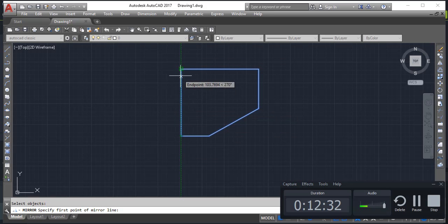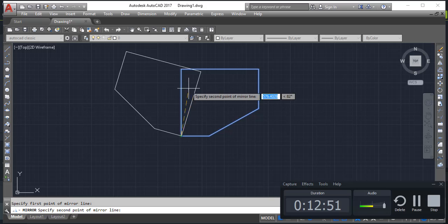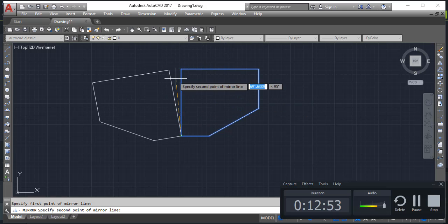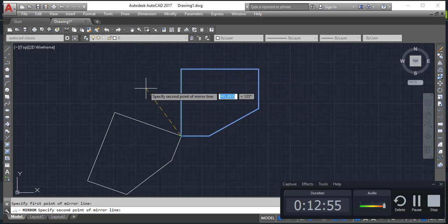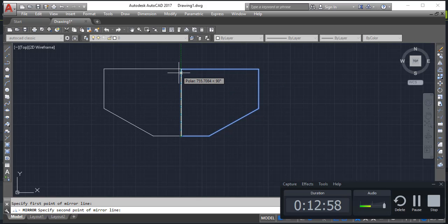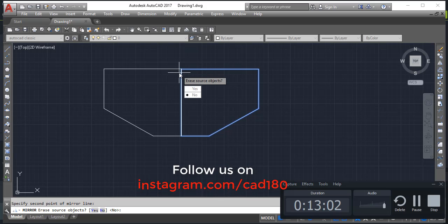So I just take this line for my mirror portion because I want these portions of this drawing to cover up to the other portion. Okay, so I have to click the base point. I just choose enter. Whichever portion you need, you can rotate. The desired portion you need to apply to that drawing. So I just click. So you have two options after clicking.